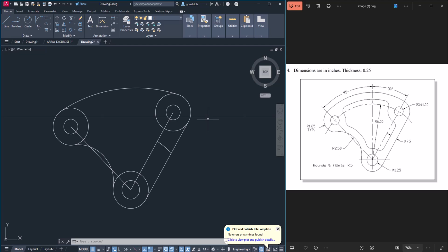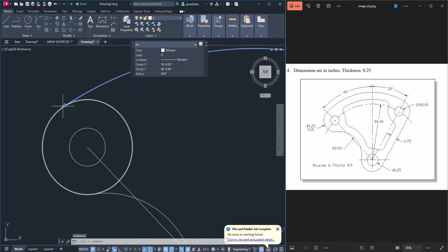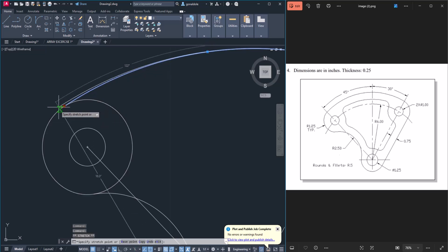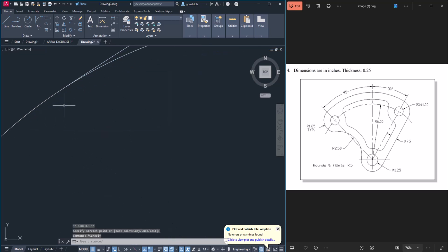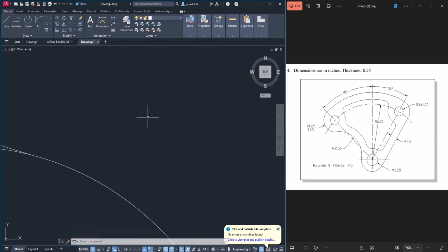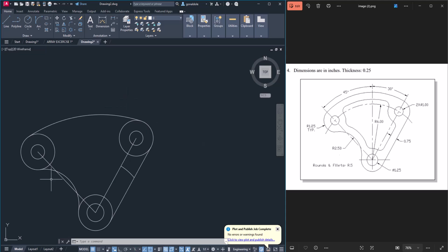So now all we just have to do is to make sure the lines are tangent to the circle. So try to locate the tangency lines, and yes, I think it's here. It's tangent here because they are lying on the circle, but they are not touching it. So we got the tangent right. So let's take off all unwanted lines, and at this point let's trim.